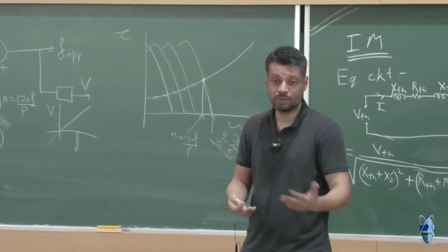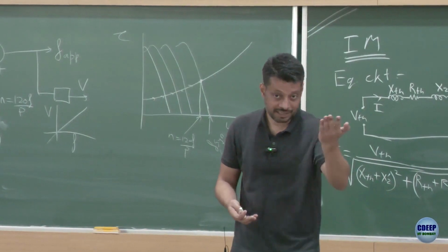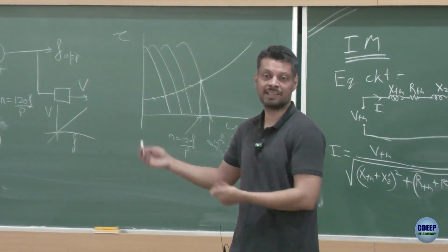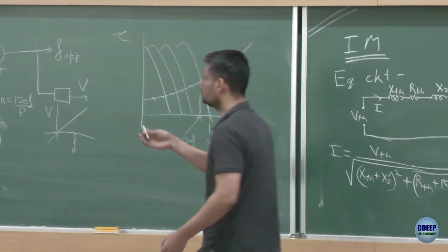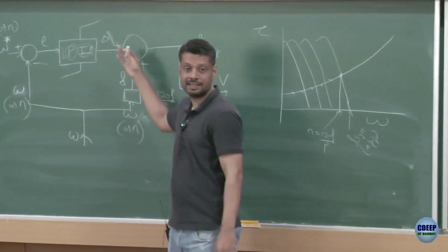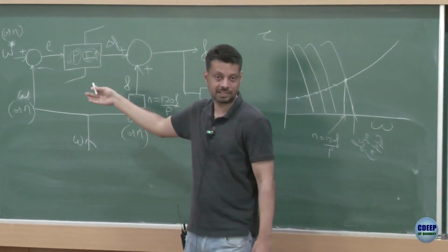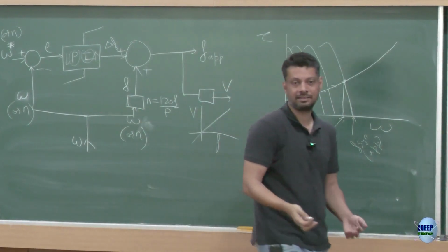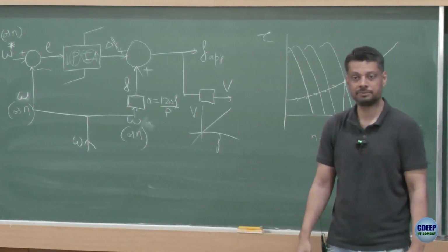What it is doing, it's doing the job what we would have done, right? You would have seen the speed is low, increase the frequency, this guy is doing the same job. Now, this guy can do that job much faster if you use PID, this guy can be very sluggish if you use only integrator. So, depending on the application you can choose, you can design the values and coefficients, right.